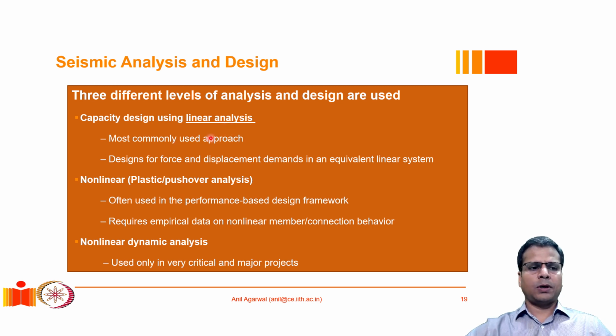This is the most commonly used approach, and the idea here is that even though we expect the system to behave non-linearly, we expect the structural system to form hinges, we design the individual components only up to the elastic limit, and then we use some kind of scaling factors to calculate the actual performance of the structure.